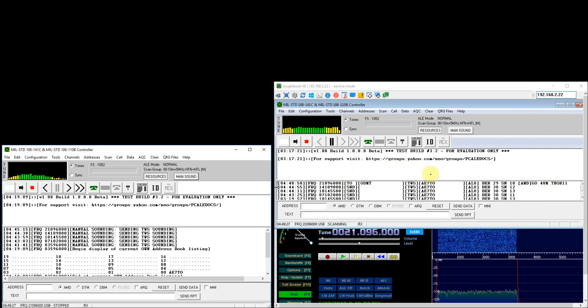You've got automatic scanning by a bunch of receivers, one at each station, and you've got manual sounding from each of the other stations. The reason for manual sounding is it allows you to have lots of time to match your antenna to your transmitter before you press sounding. If you do happen to have a station that's capable of rapidly switching to a new band and immediately transmitting on that band, then by all means use the ALE software the way it's designed. You can put both transmitters and receivers in full auto mode. You don't need separate SDRs, and everything will work the way the designers intended with this software.